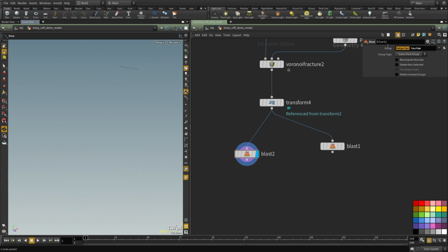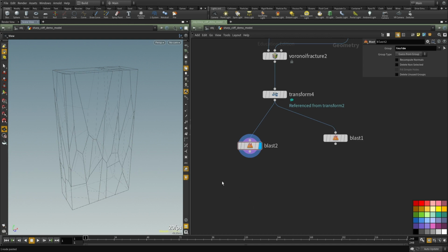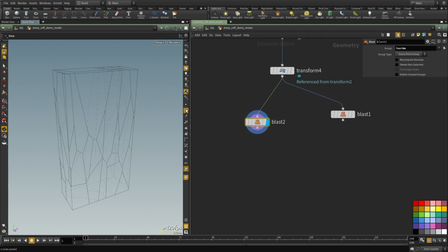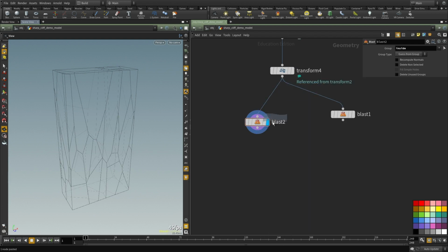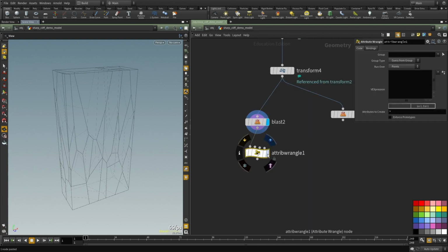Inside. Sorry. And I'm going to copy. So we have the normals here. I'm going to copy this normal into a new attribute. We can use an attribute create, but for the sake of time, it's much faster to do it through the wrangle. So we're gonna create temp n and simply equal to n.